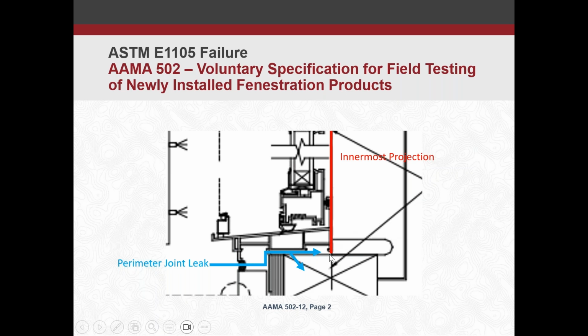You can see in this image it looks like a sill is in place here. For this type of testing, you wouldn't want that there. There should be no interior finishes installed on a unit or around a unit when you are doing these tests.